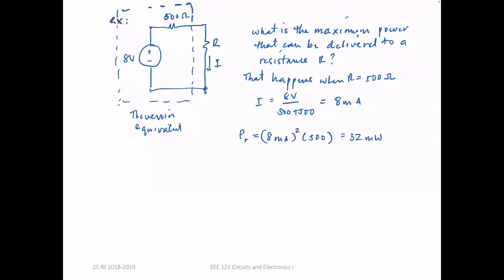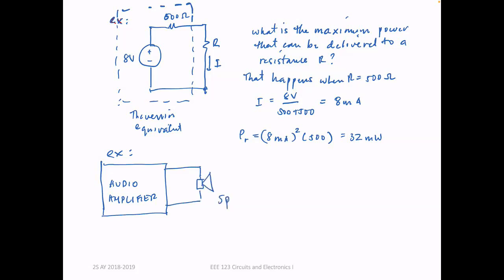For example, if this is an audio amplifier, and you want to connect a speaker to your audio amplifier, if you want maximum power to be delivered to this speaker, the resistance of the speaker should be equal to the Thevenin equivalent resistance of the audio amplifier.